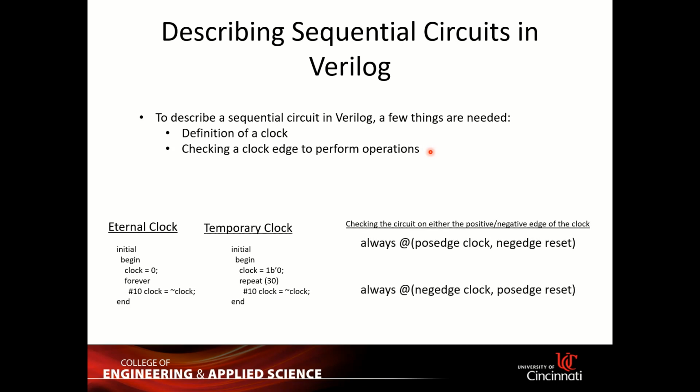So for example, a good way to check it is to use the keyword always. Do you remember this keyword always? We used it when we used the if-else behavioral modeling for Verilog. This keyword will scan a particular pin or a particular signal to see if there's any change, and if there's a change, it will respond to that change.